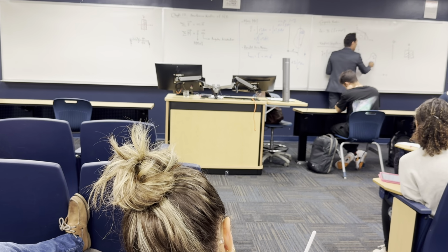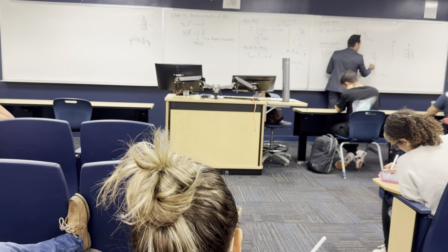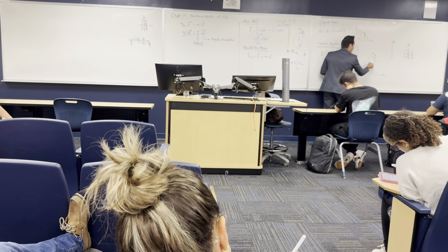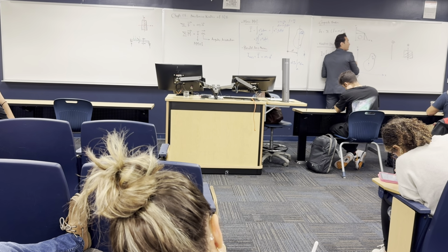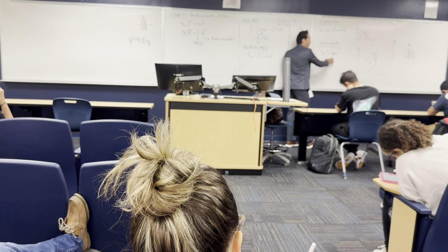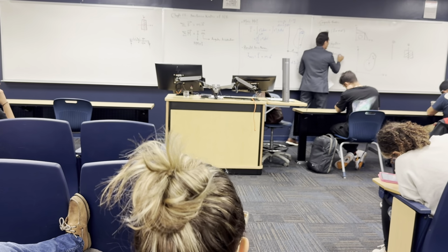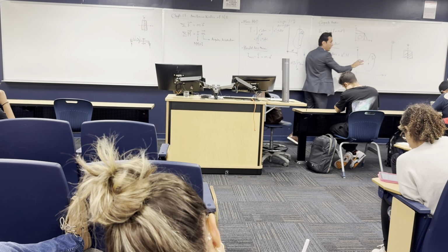So that's why we get it about the CG, for example, here. Once we get the mass moment of inertia about the CG, we multiply all the mass as one single mass by the distance squared so that we can transfer it about y. Let's say that we get this value. We make this value equal to something called k squared multiplied by all the mass, without doing any integration.